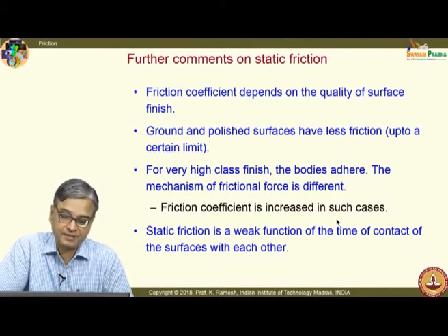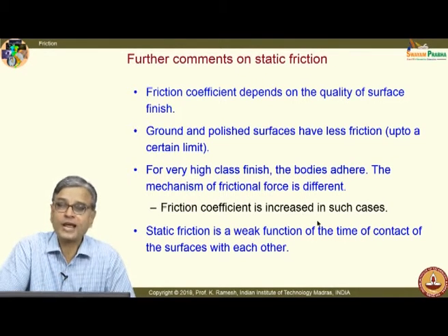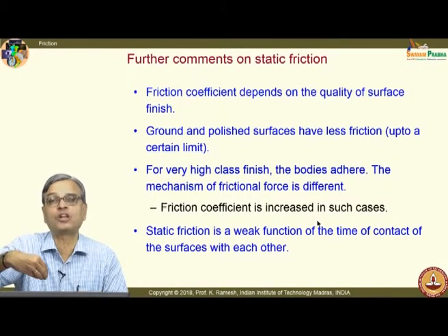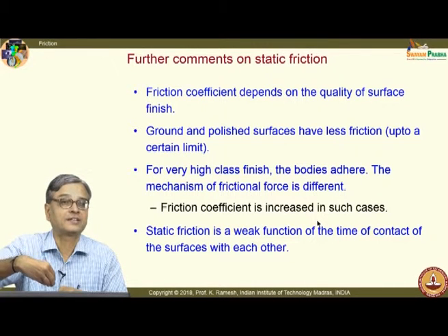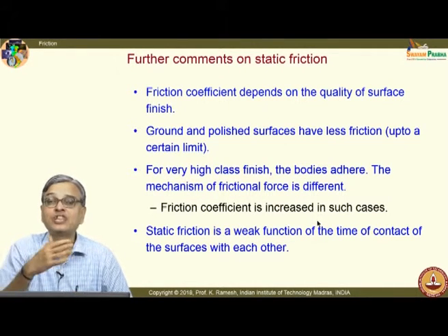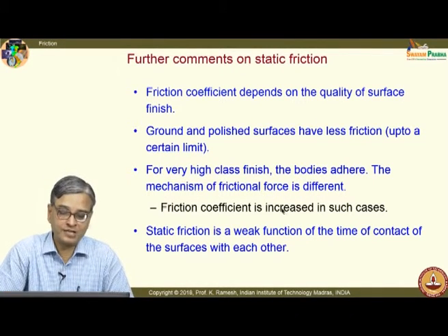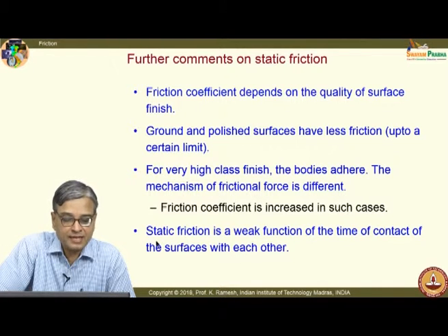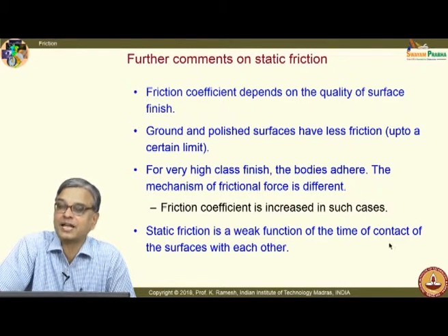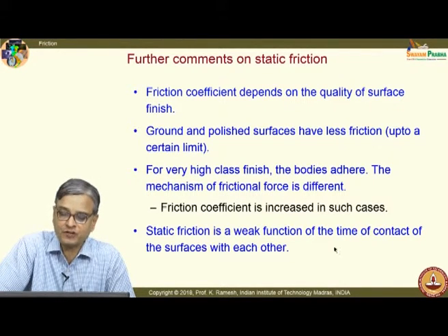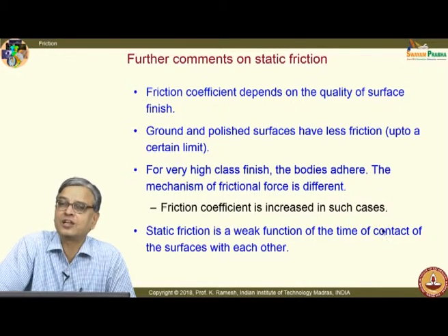And another question is, what happens if I have a normal force acting on the object, does the length of time have any influence on the frictional behavior? And what is observed from experiments is static friction is a weak function of the time of contact. It is a function of time, but it is only a weak function. So, for all practical purposes, I can neglect the time of contact of the surfaces for analysis.